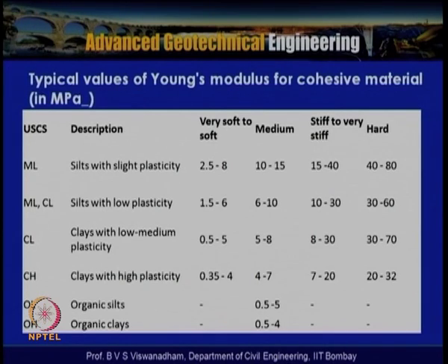In case of the Tresca, it is also indicated as a hexagonal cylinder. But we have seen that as far as soil in compression is concerned, all three, Tresca, von Mises and Mohr-Coulomb criteria, were found to coincide, but as far as tension is concerned, the value predicted from the Mohr-Coulomb criterion was found to be on the lower side.